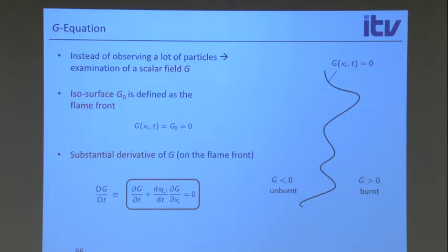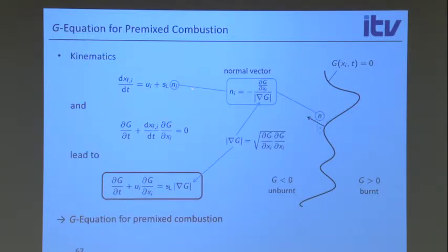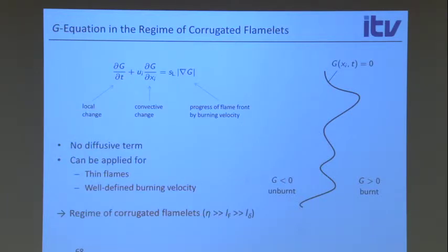We take the substantial derivative, set it equal to 0, and then we replace this by the equation I just showed, and then we get this level set equation. And by also defining a normal vector here based on the level set function, that's what we derived yesterday, I think. And so that just describes the dynamics of this flame front that propagates normal to itself.